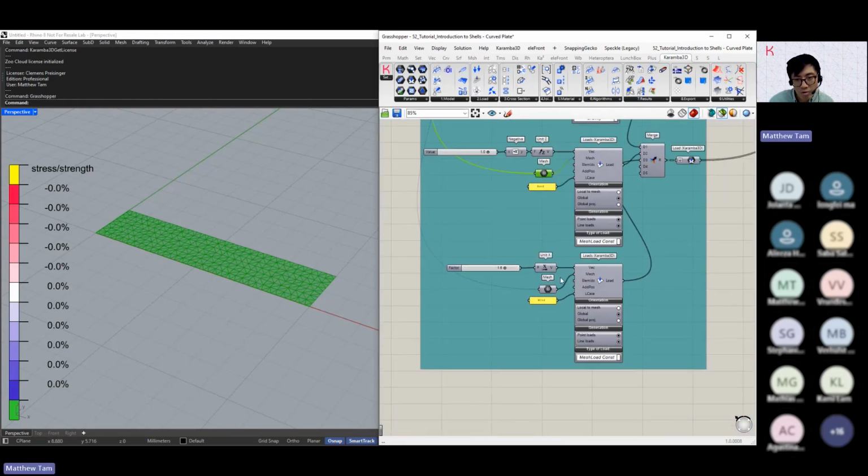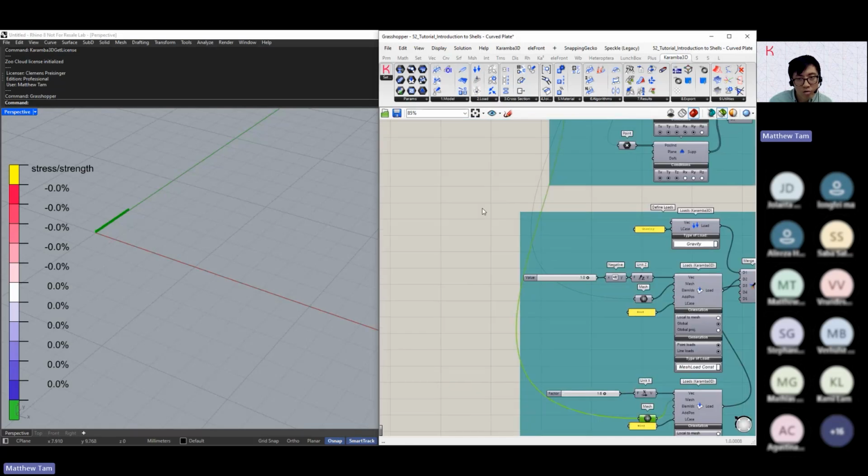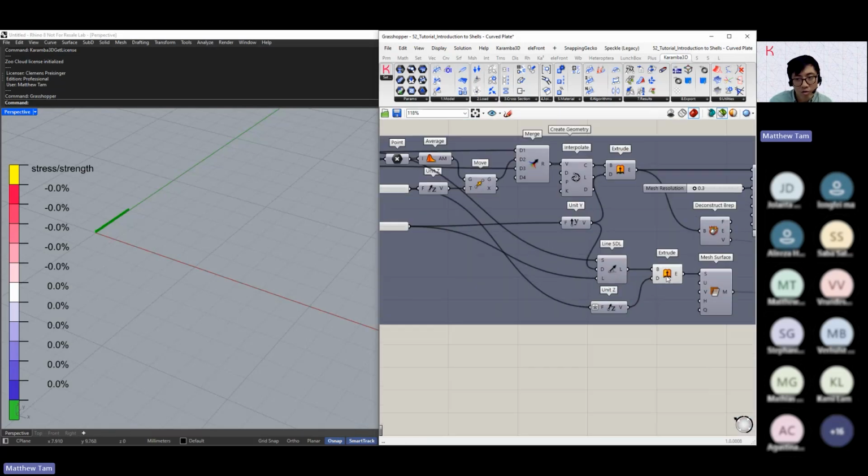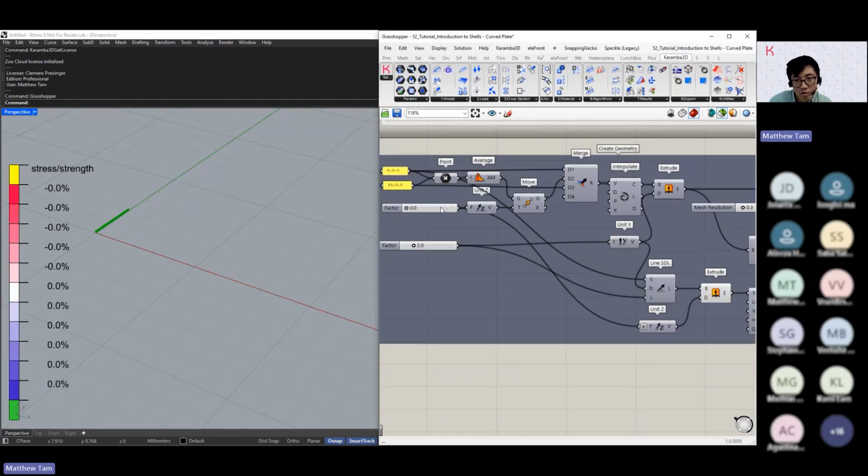In this case, because we're working with a mesh, only point loads will be generated on our mesh. Lastly, I'm also going to create a small wind load, which is actually defined as a strip on one end of our element. It's also parametrically linked, so it creates an actual extrusion from our surface. So if I was to then, for example, increase the height of my shell, you can see that it actually increases as well.